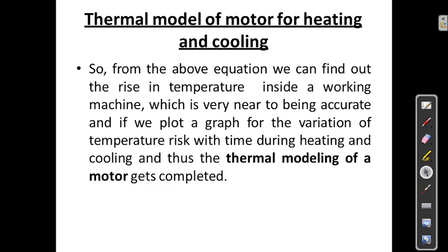From the above equation, we can find the rise in temperature inside the working machine, which is very near to being accurate. If we plot a graph of the variation of temperature with time during heating and cooling, the thermal modeling of motors is completed.